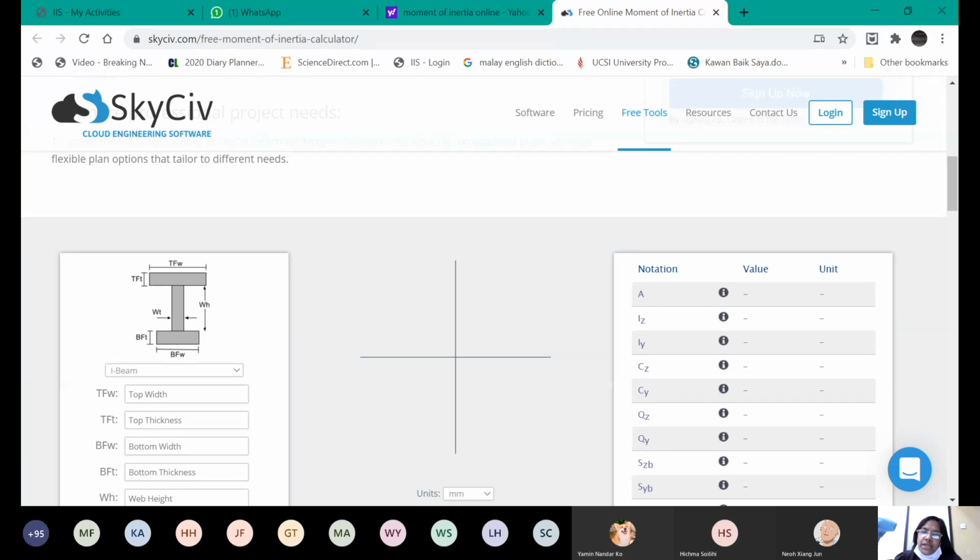It's all about the material content or weight of the material inside. This is important when you want to use a member as a column, beam, or slab. You should know the moment of inertia of that particular member. It is all written in the code book. Later, when you go for steel structure or RCC structure, you will directly refer to the code book. You can have the section, dimensions, and values. How to read the table and the manuals is what I'm going to teach you now, when you go for designing and choose the section for your construction.